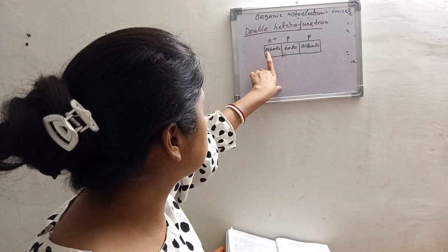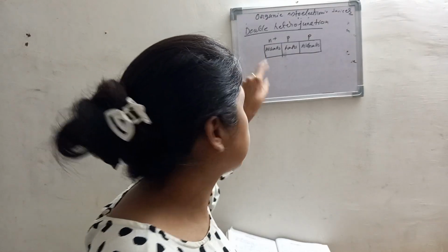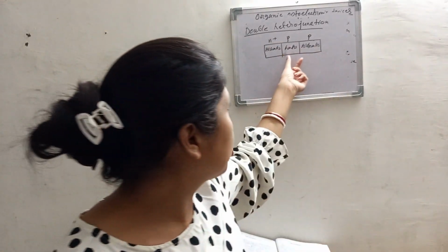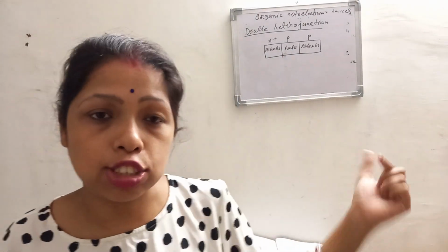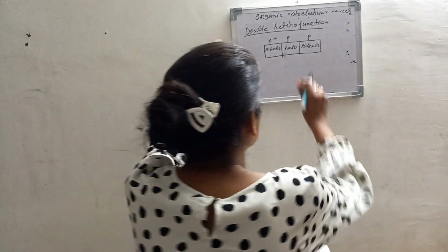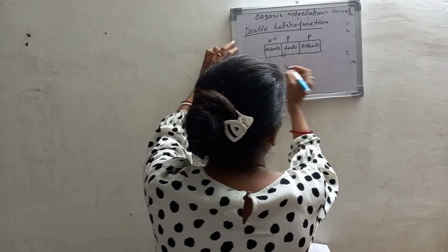Compound semiconductors. N-type means these N-type impurities are doped inside the aluminum gallium arsenide, which is highly concentrated, and the P-type gallium arsenide and P-type aluminum gallium arsenide. The width of this layer, the gallium arsenide layer, should be narrow as compared to the other layers, right? So how will it affect the performance of the device?